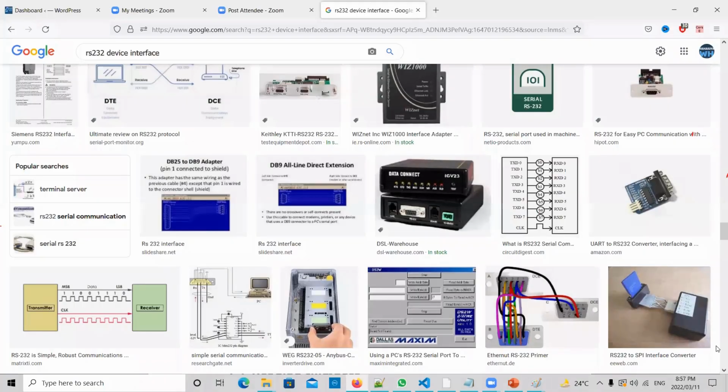How will you bring a code from a PC to the microcontroller? Let me tell you another example. You have written a microcontroller program on your PC, but you have to flash that program to the microcontroller. From the PC, you cannot execute it because the PC is not a microcontroller, it is a microprocessor. So what you do, you use something called flashing. If you take a PIC controller, you have a PICkit 2. Maybe in Atmel and 8051, they have their own flashing software.